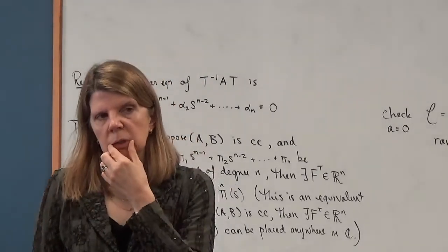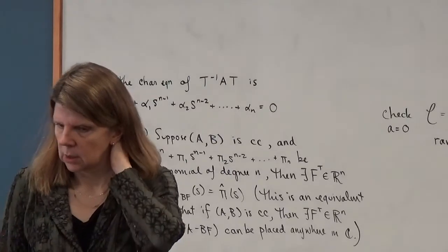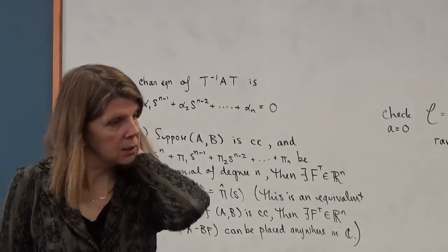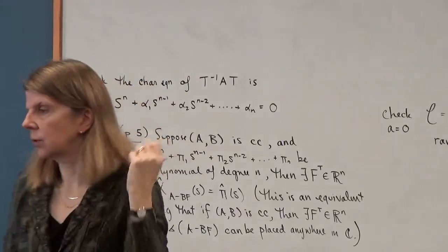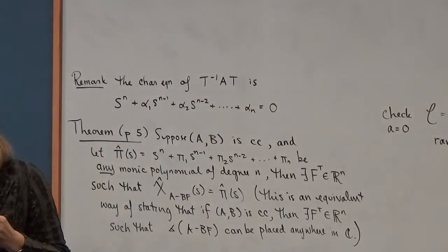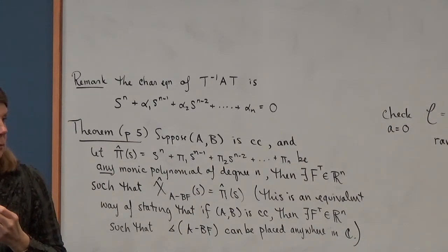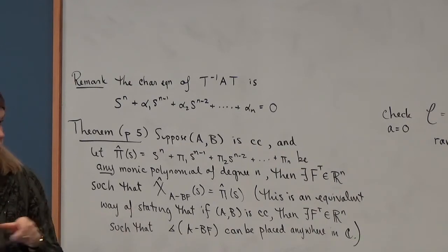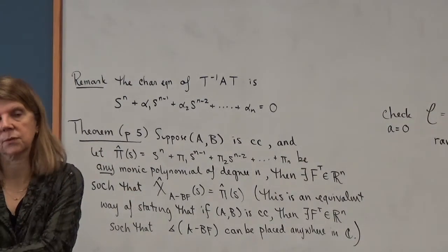Even if it's completely controllable, when would you want to shift the eigenvalues that are already stable? Like this example we had that motivated this. I had a stable eigenvalue. I couldn't move it, but it was already stable. So when would you want to move that? Maybe move it far away from the origin. Faster, right? I think you're both saying the same thing. So shift it further away from the j omega axis so it becomes faster.